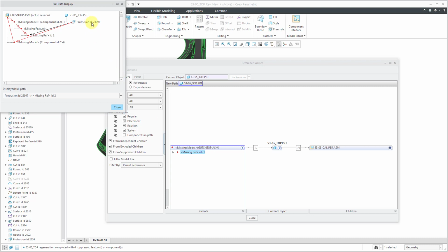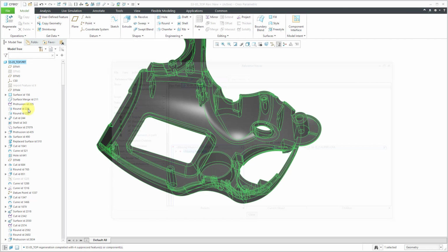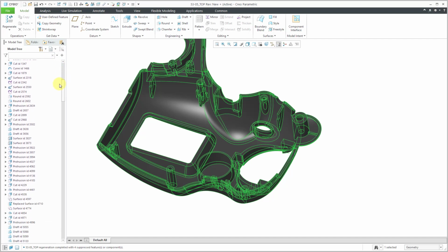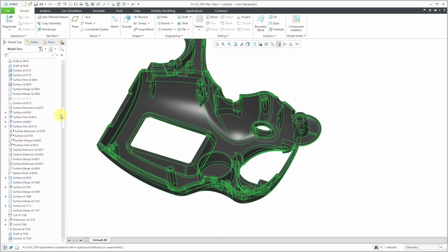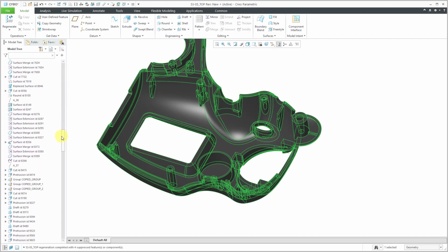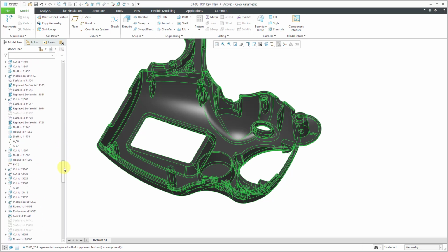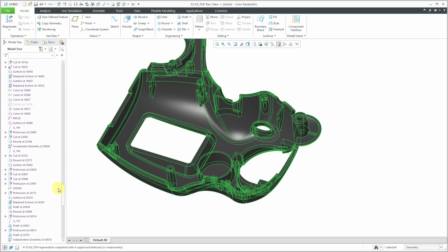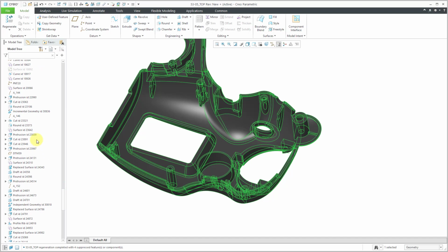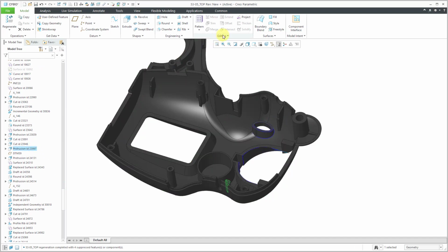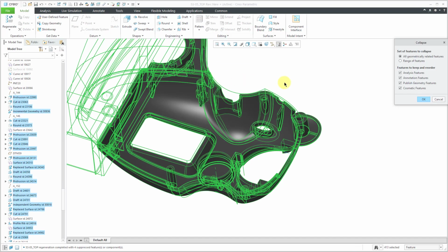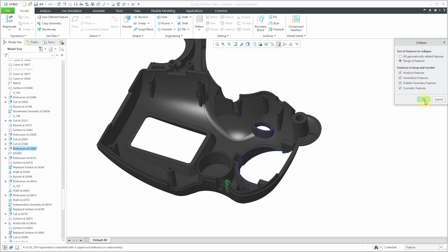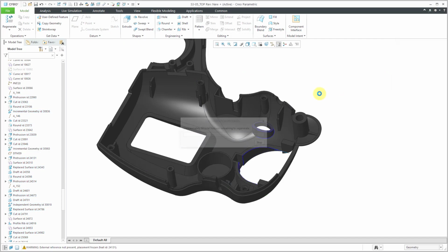And so, okay, here is that same protrusion that came up again. It's got another issue now. That was the first one that I took care of. So again, if I have the same feature that shows up more than once, then I'll use the situation where I will just collapse that feature entirely. Okay, here it is. Once again, editing, collapse. Just change it to range of features for that one feature.